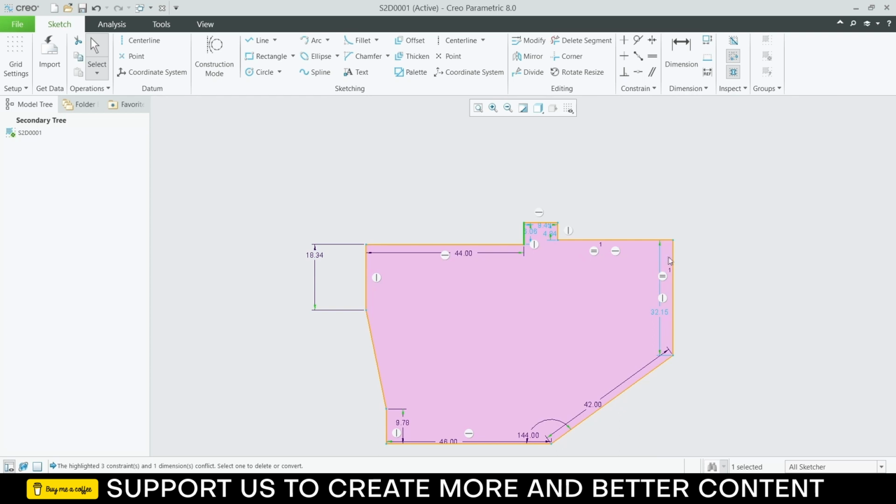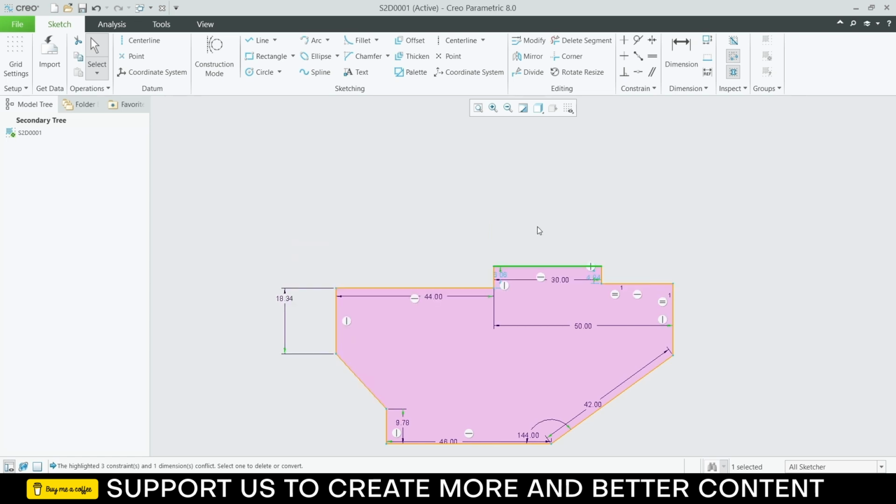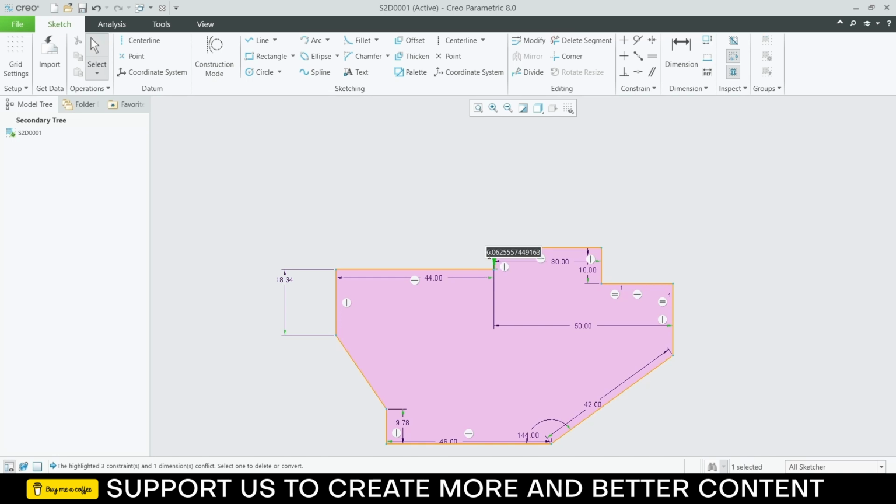By pressing Ctrl, select these two. Click on dimensions. This is 50 mm. This is 30 mm. This is 10 mm. Double click on it, and this is 18 mm. So I have made the sketch, and this is how it looks like.